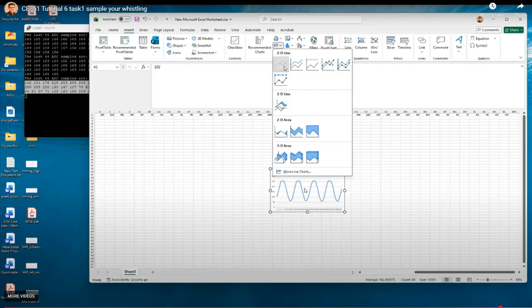It could be either your whistling is not loud enough, so then just use a YouTube video, play the audio, so you don't have to whistle by yourself, and you have to move it very close to the microphone. So for example, the speaker of your phone playing that audio, you just move it probably no more than this much next to your microphone, the microphone on the board, so you can get a decent sound wave. It should be a waveform that is very similar to a sound wave like this.